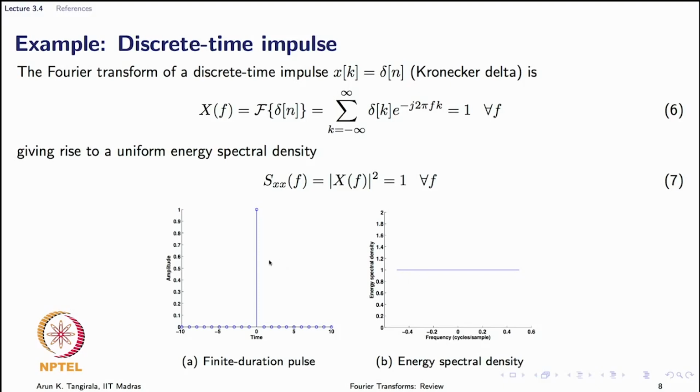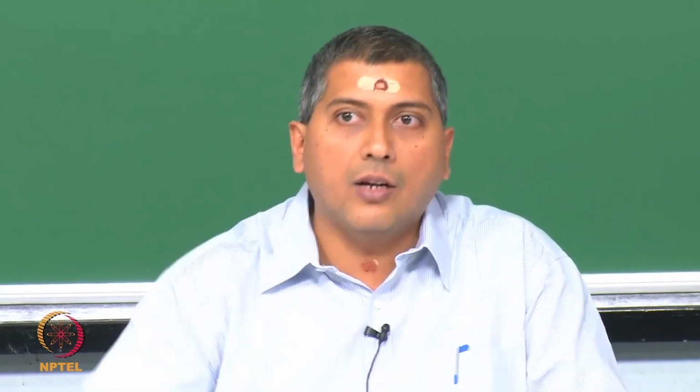Well, the signal plot is also the same as the energy spectral density plot in time. Again the same observation that we made yesterday: when we have a highly localized energy density in time, or very finely localized, we have a very broad spread of the energy density in the frequency domain. In fact, it spans all the frequencies uniformly.